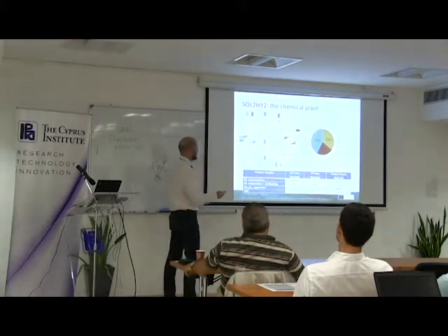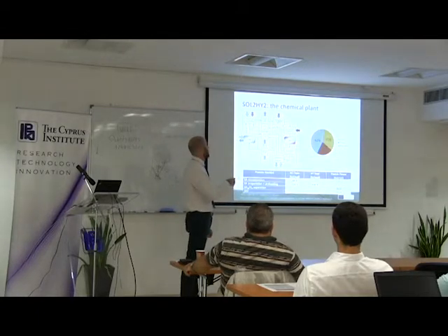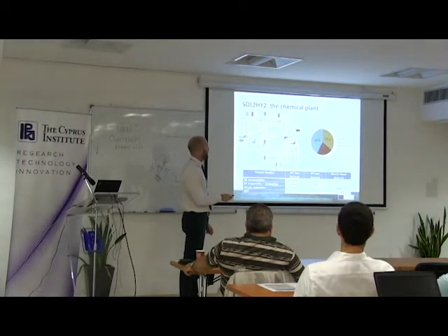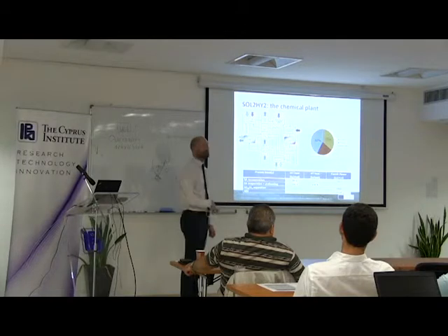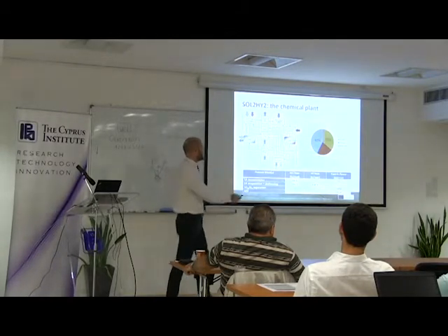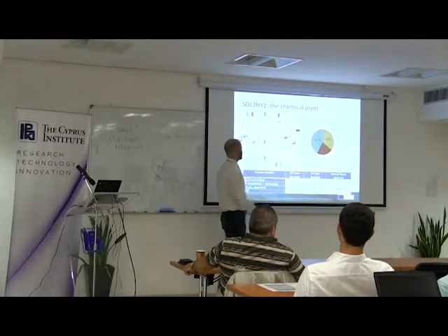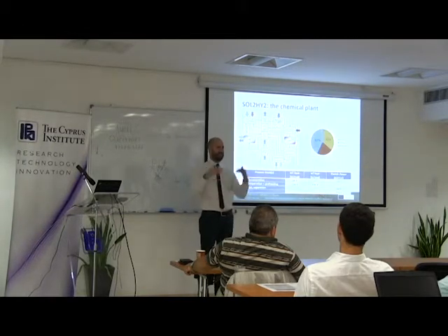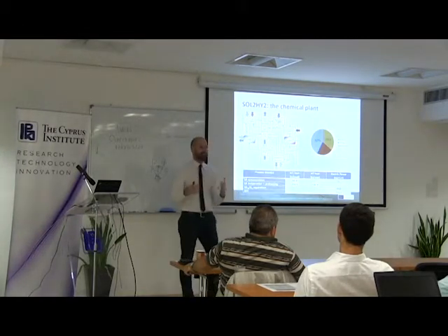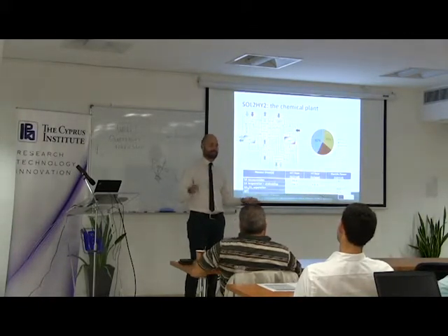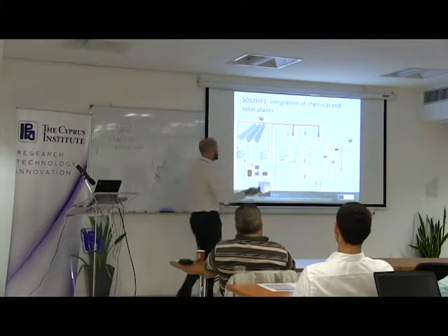This is the process block diagram. We do not go into details. I just want to show you that the input required is 42% electricity and the remaining is heat. High temperature heat, 23%, and medium temperature heat. By medium temperature heat, I mean heat below 550 Celsius degrees, which can be provided with a molten salt storage system. So this is the concept of the plant.